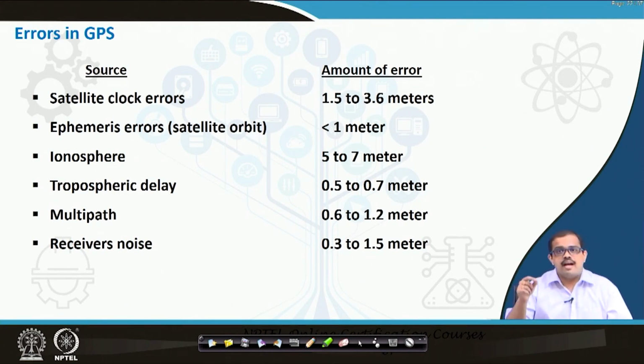Other than these are the errors due to the human himself or herself when he or she is on the field, in case you are collecting or validating data. If you are collecting data or looking at data acquisition through the GPS signals onto your receiver, there are errors because your receiver has a certain precision, and certain errors are induced. The second thing is the way you are collecting the data. The third thing is the way the receiver perceives that particular data.